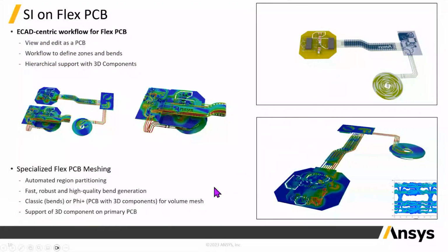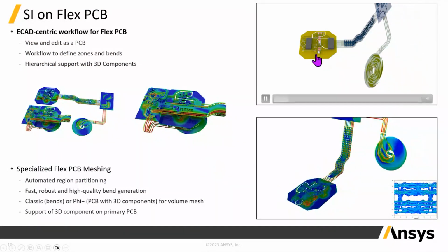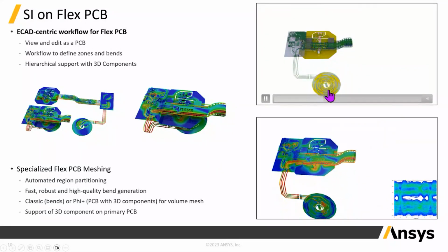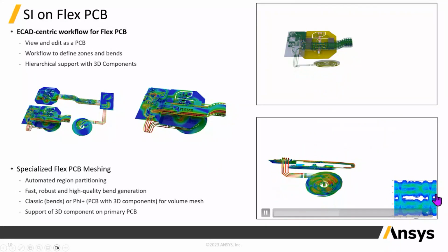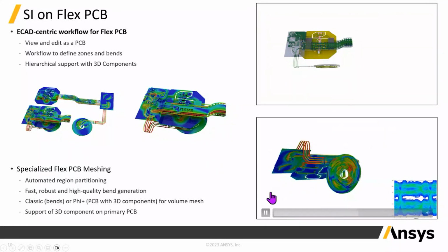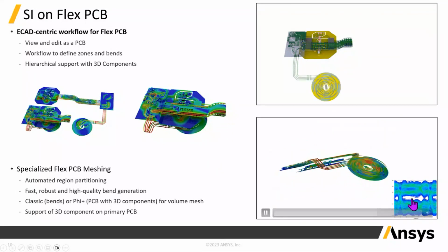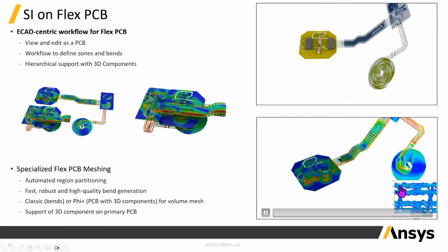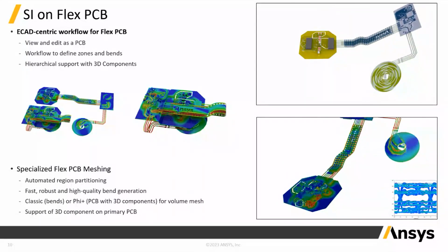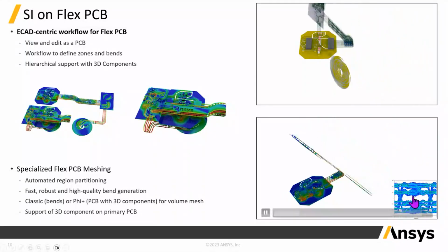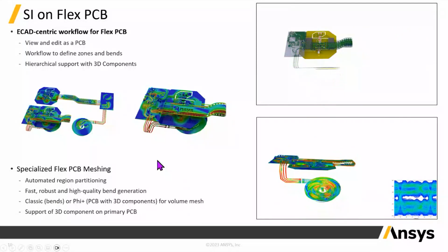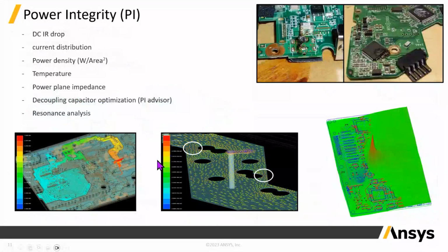Another kind of application, which is very common for electronic gadgets, is the flexible PCB. When you have a flexible PCB, you can design these kinds of movements, rotations and bending, and you can see how the eye diagram is going to change when you fold it at different angles. You can see right now this is better, and when the PCB is bending very tightly, because of the cross coupling your eye becomes more and more closed, and you are losing the communication. So you can virtually verify this kind of flexible PCB using the tool.